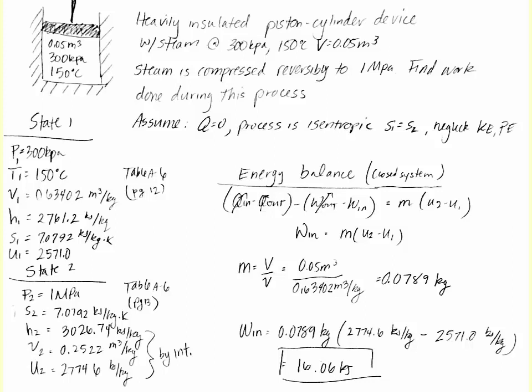There have been some exceptions with the piston cylinder device where we have come up with something similar, where if we have heat transfer and this boundary work, for a constant pressure process, we can say that this boundary work PV can combine with this U term over here on the other side of the equation to have an H in there, but that's a special case.